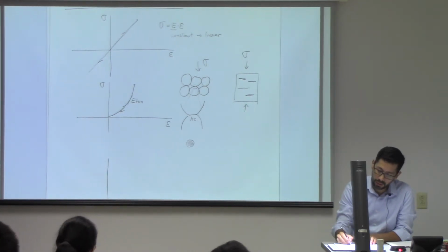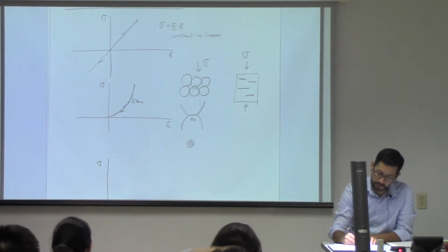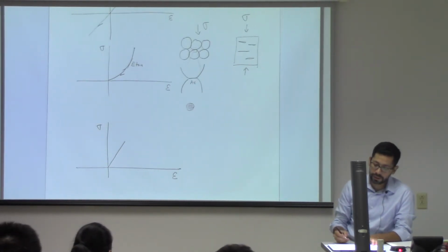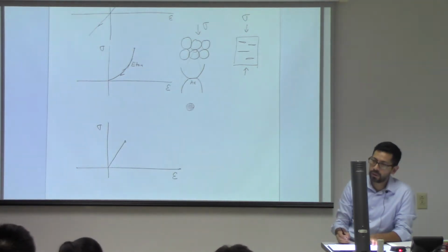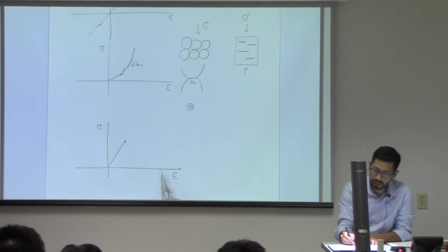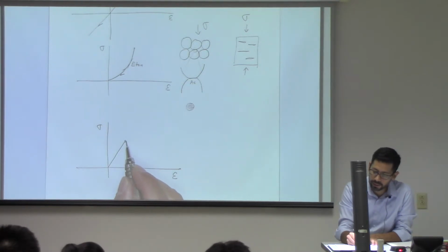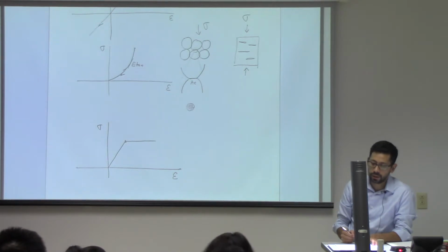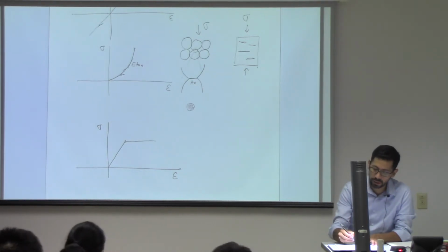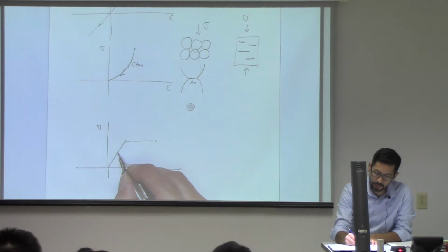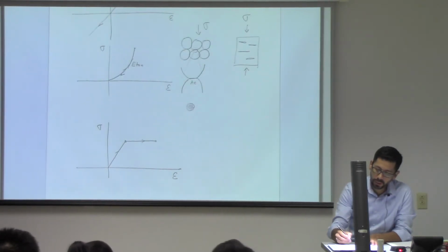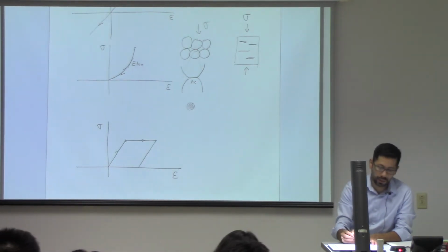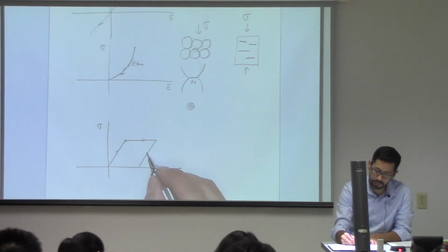On the other hand, when we go to inelasticity, we go into materials that you can load to a certain amount, but at some point you're going to get to something which is called the yield stress. And at that yield stress, the material can deform with no additional increment of stress. And if you were to unload this material, we can idealize it as going down with the same slope as it went up.